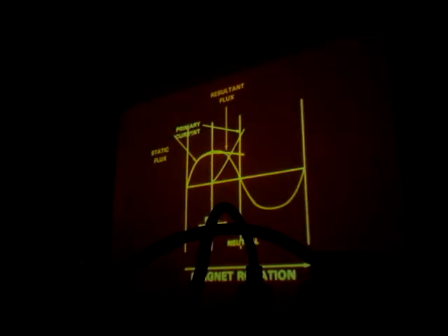When current flows in the primary winding, it also produces a magnetic flux, which, according to Lenz's law, opposes the change that causes it. And the final or resultant flux causes the primary current to reach its maximum. This does not occur at the neutral position of the magnet, but instead a few degrees beyond neutral of magnet rotation.